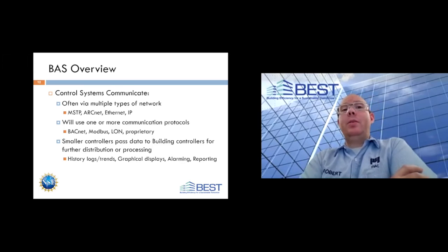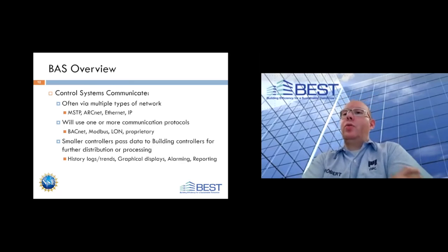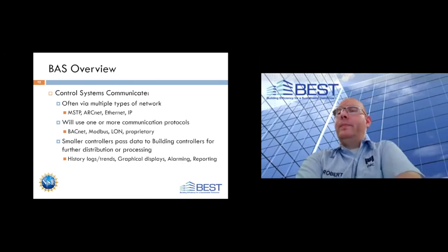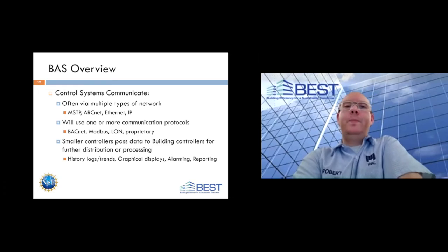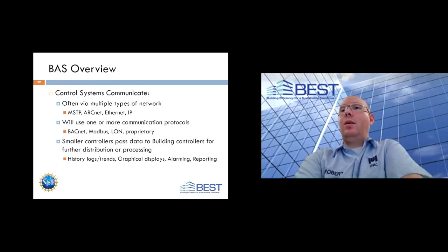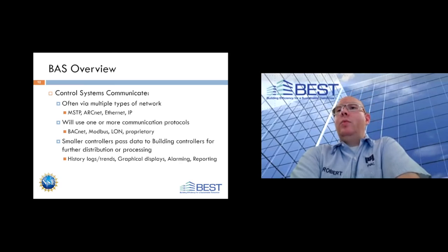Also still very popular in the US is LON communication, or Echelon. I believe it is still the most popular climate control communication protocol in Europe. Originally designed for the smart kitchen so that your toaster could talk to your refrigerator, amusingly. There are massive amounts of LON controllers installed all over the world, a huge number in North America. For a long time, LON was actually the leader before BACnet took over about 15 years ago or so.